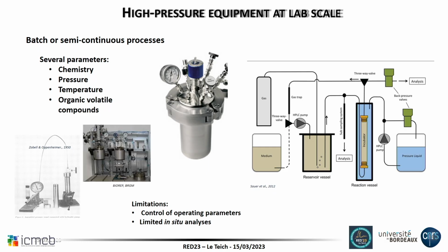Plus, when you want to analyze, you have to open your reactor. So it's one shot, it's like you cook something, you know, and then you take it out and, oh crap, I failed. So you cannot adjust or change the parameters because you don't know exactly what's happening inside, besides having information on the temperature, because you can put a temperature sensor and a pressure sensor.